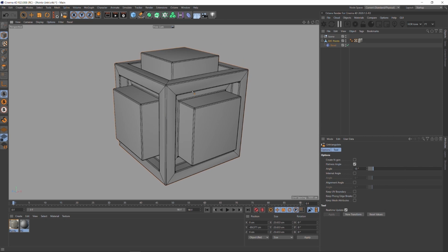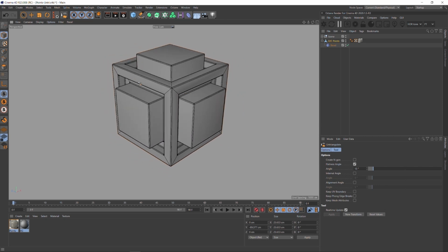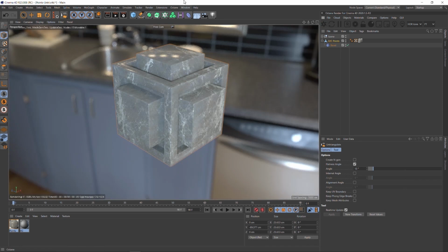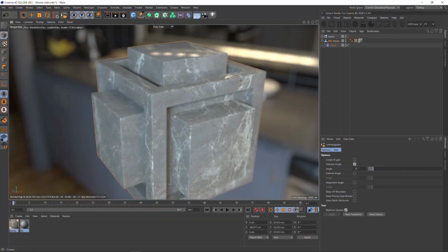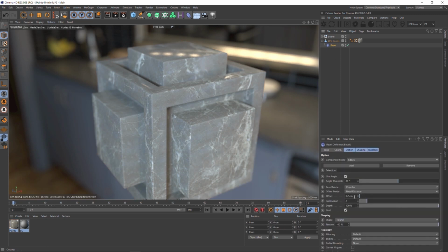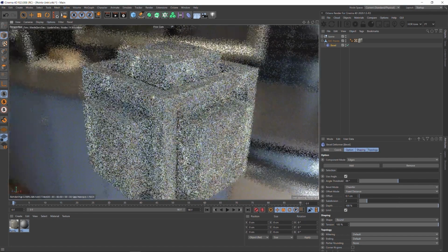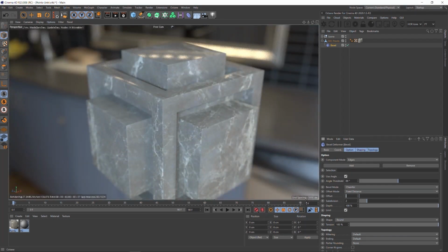And you may be wondering, why do I go through all this trouble in order to put a bevel on here? And let me just illustrate that by sending it over to Octane so that you can see the importance of having rounded edges on your models. So these are kind of large roundings. You may deal with models that work with something quite a bit smaller, but even if you go really small, you can still see that rounding, and that's still picking up highlights from the lights and giving the model depth. And that's what's important here. For realism, nothing in life has a perfectly sharp corner.